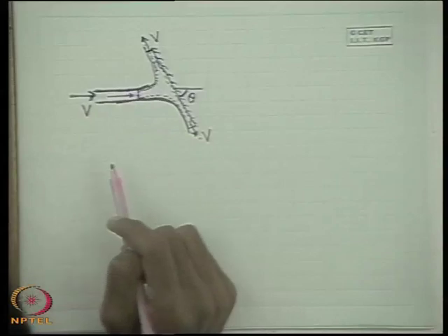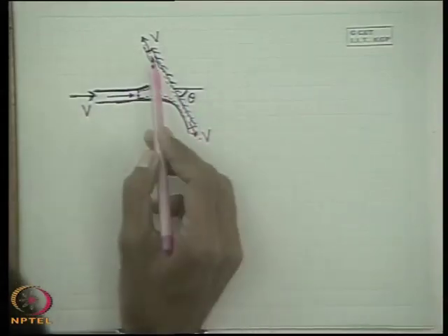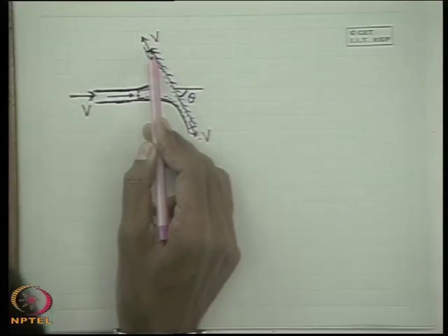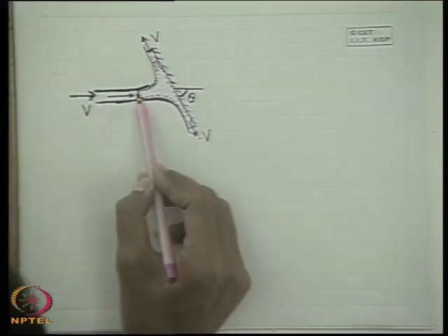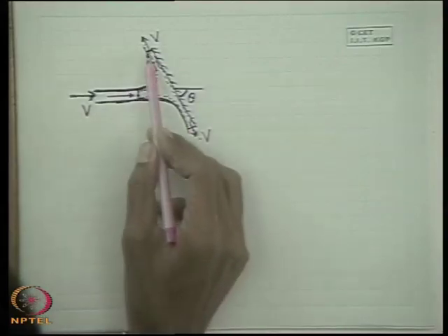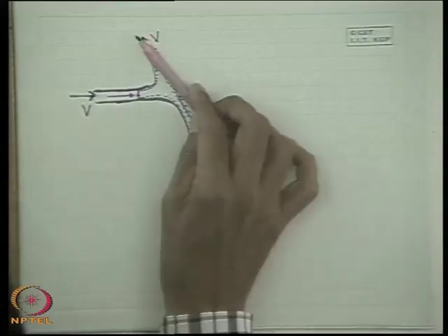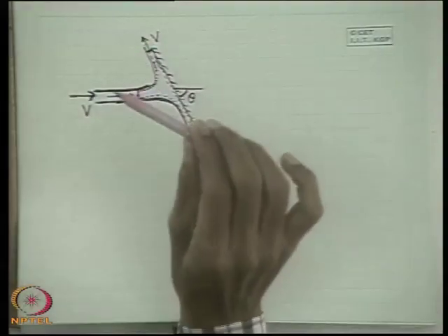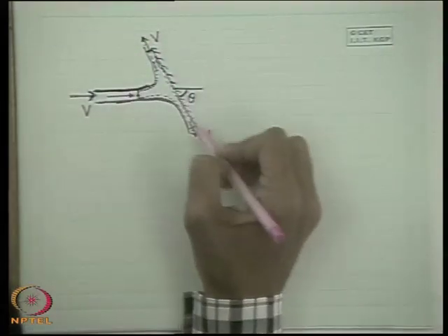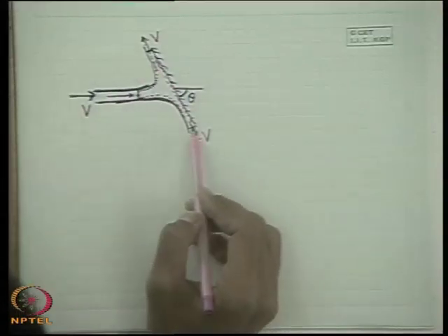But another assumption is needed: if the plate is in the vertical plane, then the elevation difference between the three planes, the inlet plane and the two exit planes, is zero. For a surface in a horizontal plane, the question does not arise, but if the surface is in a vertical plane, then the elevation difference should be negligible.